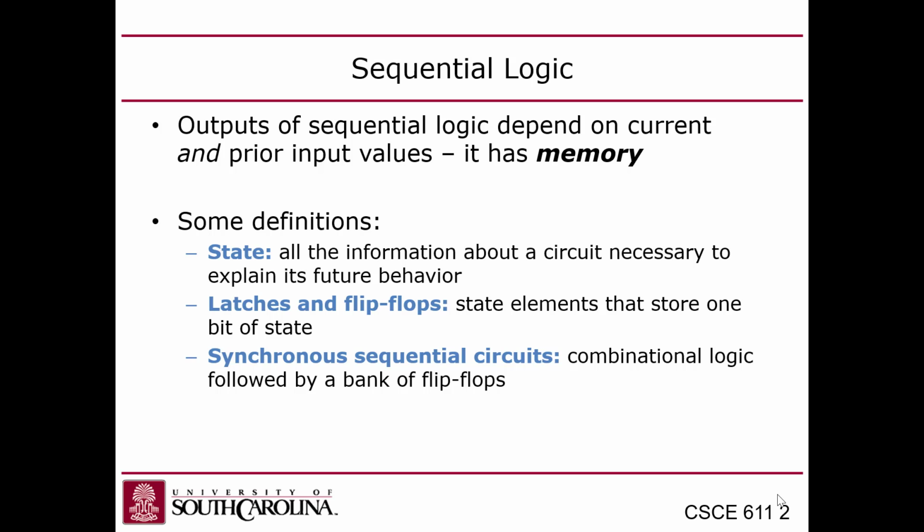You guys with me? So the state refers to the state of the controller in the sequence, where the sequence is, I have to request the bus, I have to wait for the bus, I have to do my transaction on the bus, and then I return back to idle.